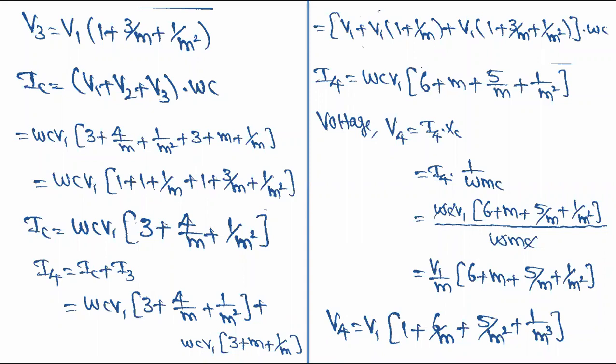That is V4 is connected to the conductor side and V1 is connected to the supporting structure, that is the cross arm side. Now at the conductor side of the insulator, the voltage is maximum and it goes on decreasing toward the supporting structure. That is V4 is a higher value compared to V3, V3 is higher than V2, and V2 is higher than V1.